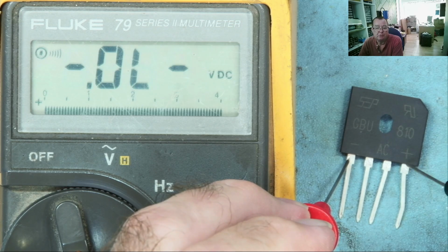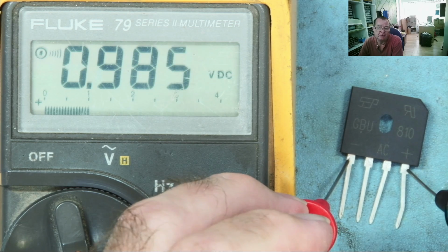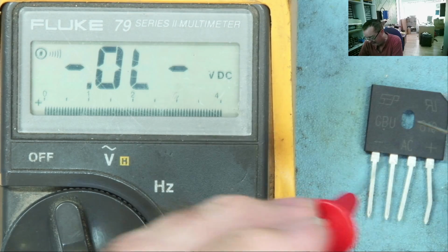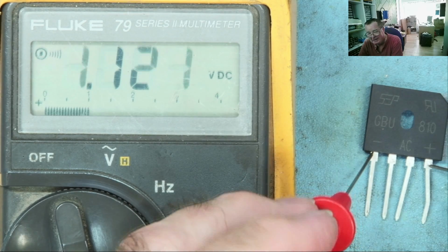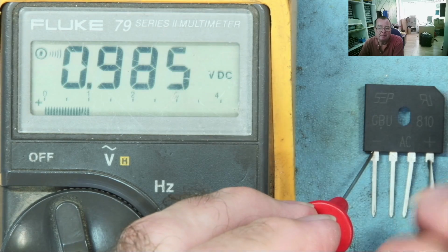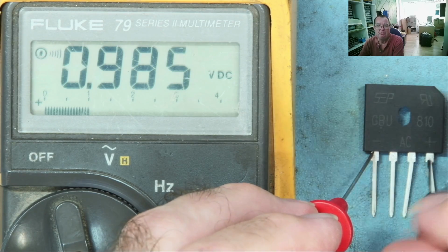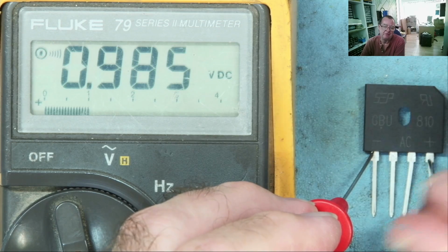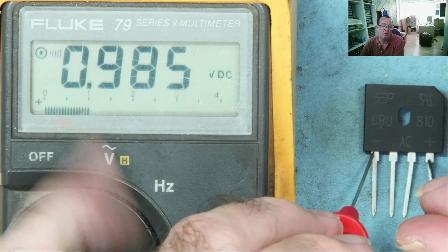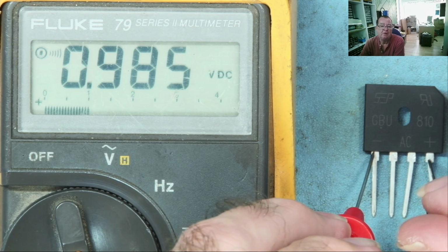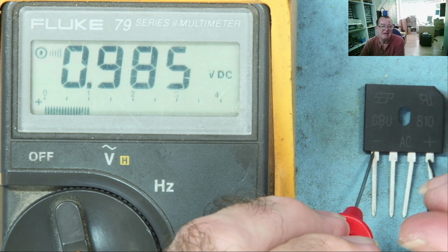If you read a short across these, you have a short on the output. So just bear in mind, if you wonder what that funny reading is, think, where is the black lead? It's on the positive. Okay, this situation will not occur when the circuit is operating normally, so you can ignore that. And that's another important point which will come in later when we look at testing components in circuit.